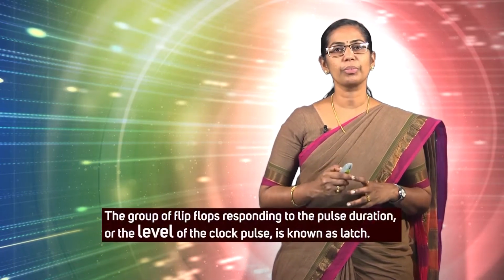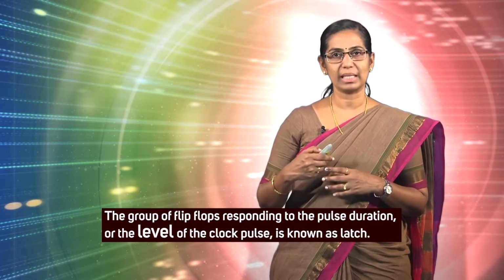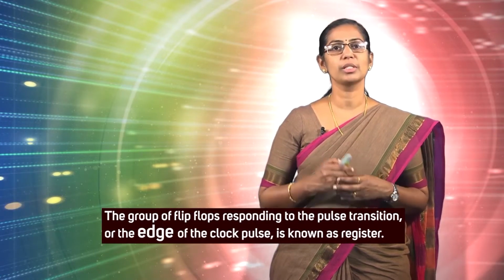Here, you must recall the difference between level triggered and edge triggered flip-flops, which we discussed in one of the previous sessions. The registers can be designed in both manners, as it is a group of flip-flops. The group of flip-flops responding to the pulse duration or the level of the clock pulse is known as a latch, and the group of flip-flops responding to the pulse transition or to the edge of the clock pulse is known as a register. In this session, we are going to discuss only registers which are edge triggered.